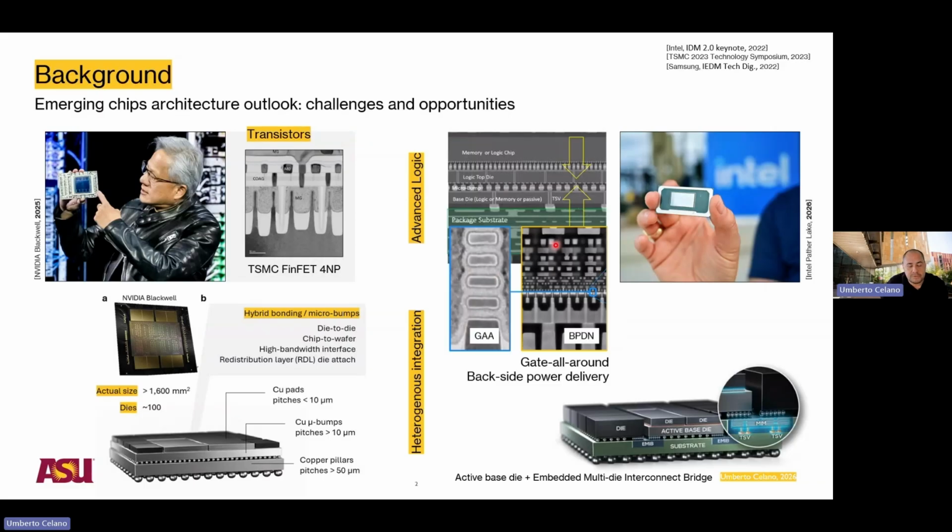But most importantly, I would say it's the first time that we have a chip which has basically wires on both sides. So if you squeeze your eyes, the front end of the line where all devices are seated is somewhere here. On both sides of the chip, you have wires. This is changing dramatically the architecture. It's also changing dramatically our ability to make complex interconnection using advanced packaging solutions. And that's the other side of the equation, which is getting very exciting.